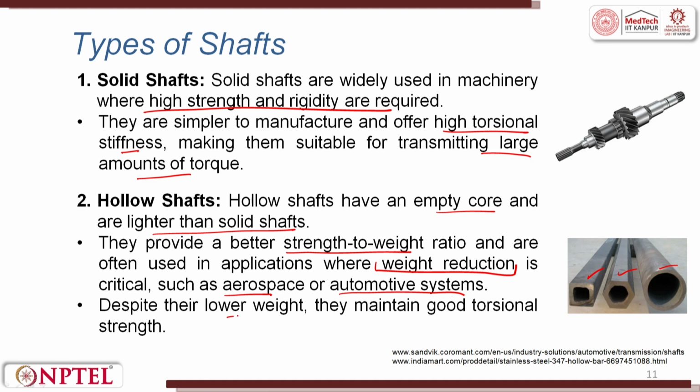Despite their lower weight, they maintain good torsional strength. This is again the law of physics. You understand, for the same material, when the pipe or shaft is hollow, it would have strength even higher than what is there in the solid shaft.